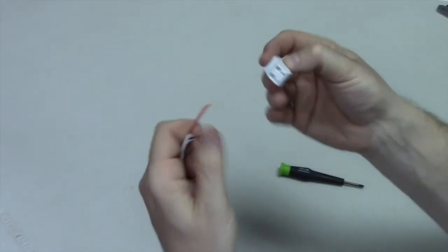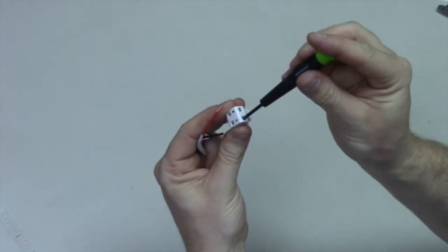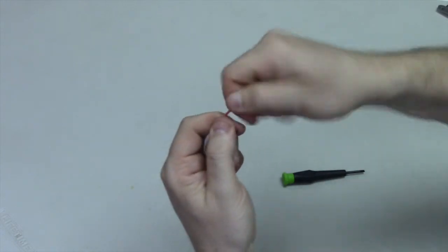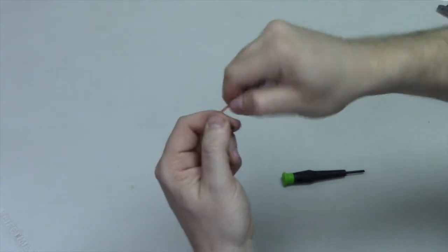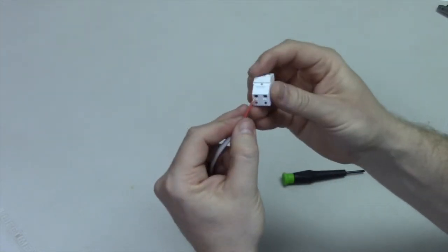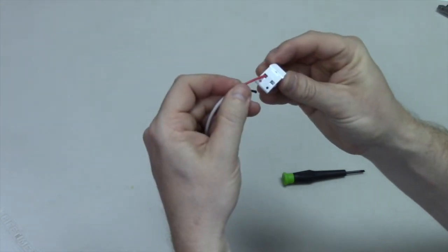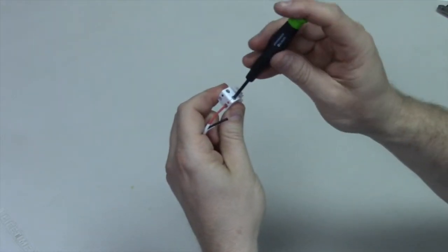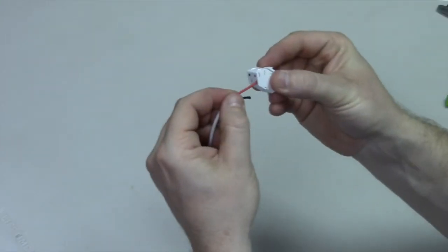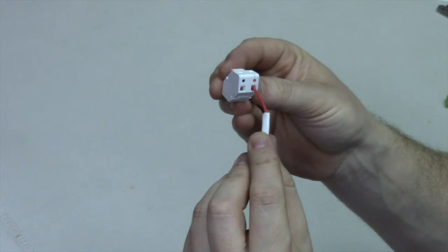Sometimes you may run into a screw-down keystone connector like this. You'll need a small flathead screwdriver. To attach the wires, you unscrew the small screws for each hole. Make sure the wires are twisted tight. Matching up the red to the red, the positive, and the black to the black, the negative, insert the wire inside the hole in the front. Then, while holding the wire in place, screw down the screws so that it pinches the wire inside, making the connection. Check to make sure it is connected securely, with no wire showing on the outside of the hole. If you have too much stripped and wire is exposed, it again could lead to a short. Once you finish one wire, do the same with the other wire.